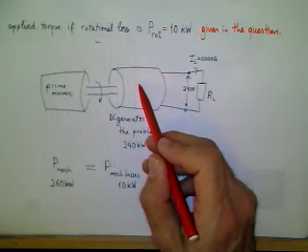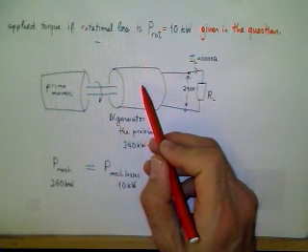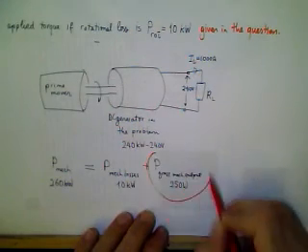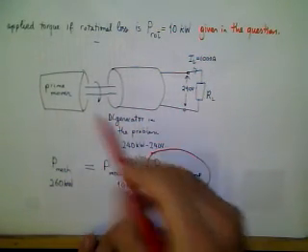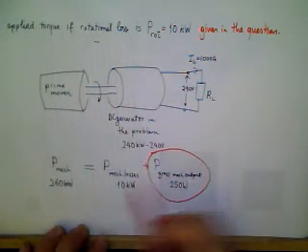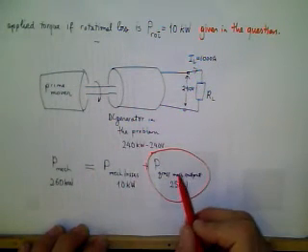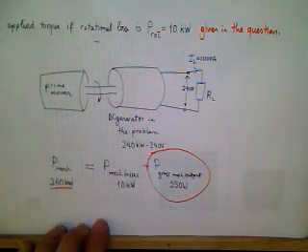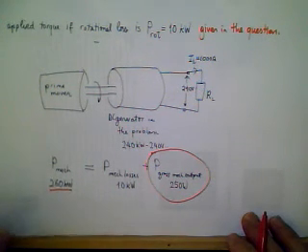The gross electrical power, EA times IA, was 250 kilowatts, calculated in the previous section. So the net mechanical input can be calculated as an output plus losses kind of equation, which ends up to be 260 kilowatts.